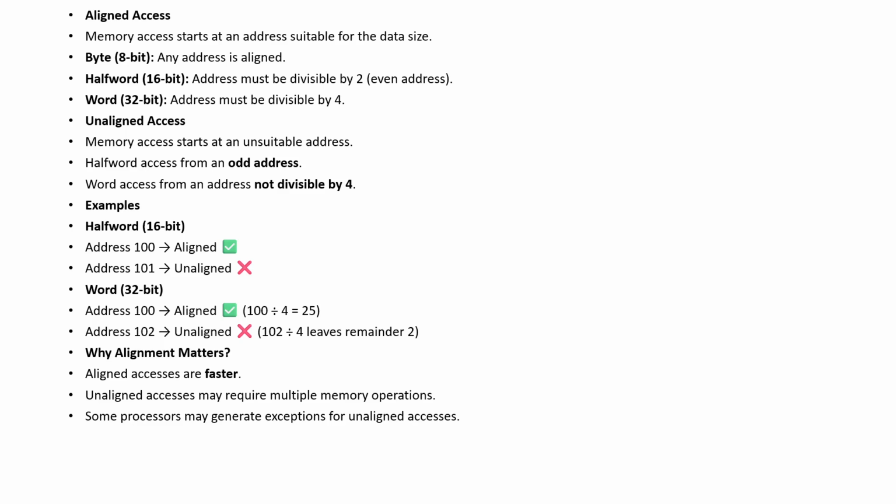But unaligned access requires multiple memory operations. Some processors may generate an exception for unaligned access, so some processors will not work for unaligned access. Thank you.